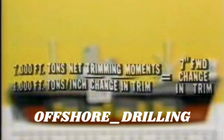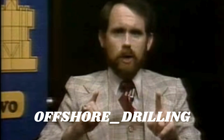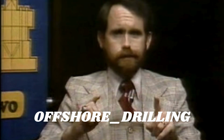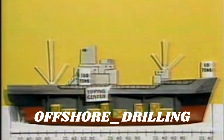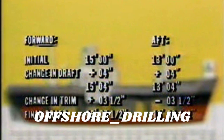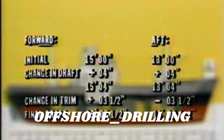If we divide the 7,000 foot-tons by 1,000 foot-tons per inch, we have a final change of trim of 7 inches by the head. Note that this is a change of trim from the original trim. So what are the final drafts and the final trim? The initial forward draft was 15 feet. This was increased 4 inches by loading cargo to 15 feet 4 inches. It was further increased by half of the change of trim, or 3.5 inches, to 15 feet 7.5 inches. This is the final forward draft.